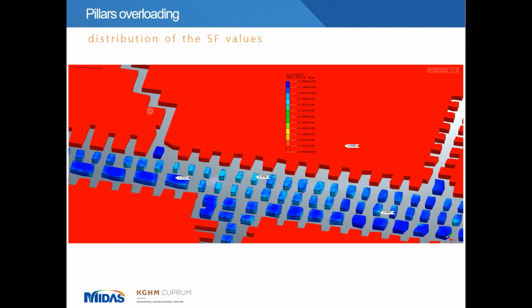On the other hand, some of the technological pillars between the backfilling areas are characterized by a safety factor lower than 1, which indicates the probability of failure. With this knowledge, you can take preventive measures, such as, for example, installing additional hydraulic roof support at intersections between these pillars, or designing pillars with larger geometry, of course, if you are at the stage of projecting underground excavation.